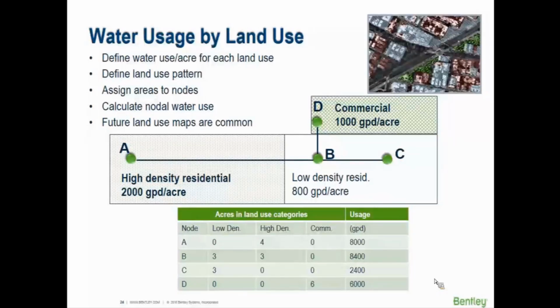You can load it by how many gallons per day per acre, because geometrically you would know how many acres that area represents, and then you could say 2,000 gallons per day or whatever demand rate you would say. That's going to be kind of one of the least accurate because you're assuming whatever that rate is per acre per area, as compared to flow meter data that is a lot more precise.